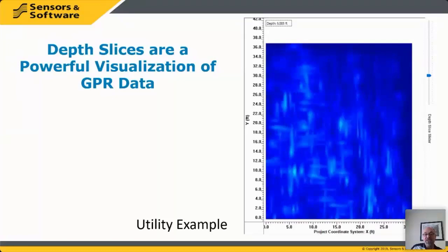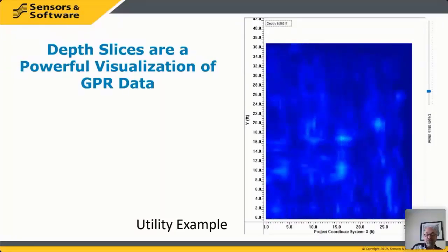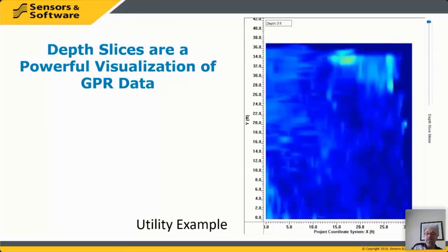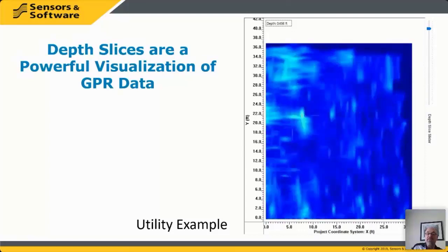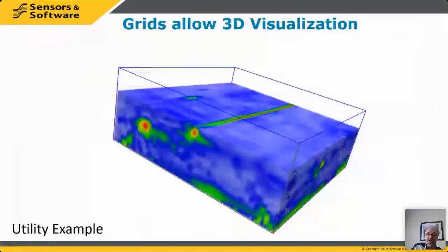And so this is the power of grids, and it's worth the time. It is worth the time. I've had many people call up and they've collected a very coarse grid and they can't make sense of it. And so do a finer grid. Spend the time out in the field collecting more data than the same time in the office scratching your head of how to make sense of the data.